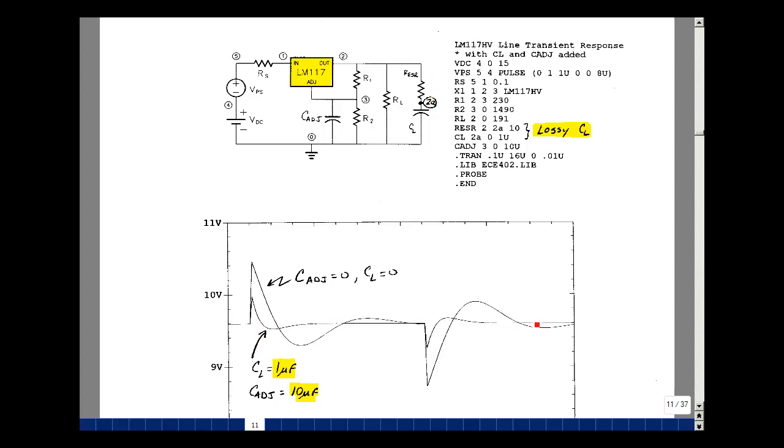And all of a sudden, everything was stable, and I began to get a curve that looked very much like my lab data. What's happening here is that when you have a pure capacitor here, this is again like a beta circuit problem. You get an op-amp circuit in here, and you basically have a lousy phase margin. Putting this here creates a 0 and a pole in the equations of your circuit. And without that resistor, it doesn't work.